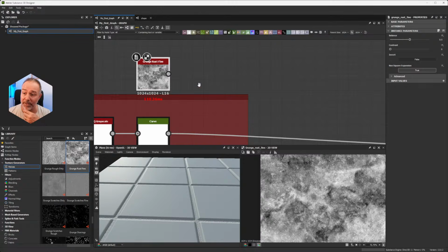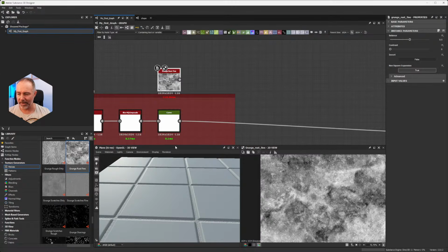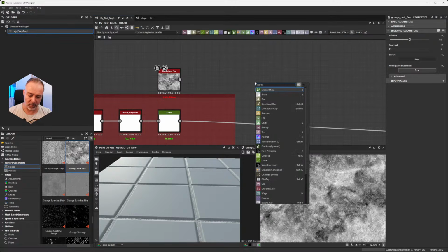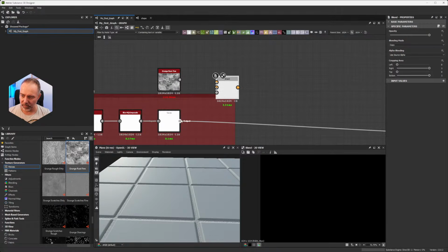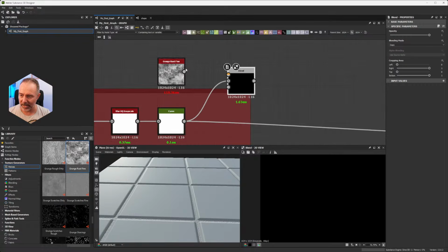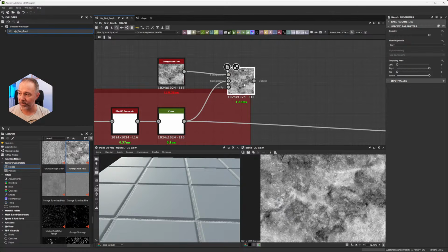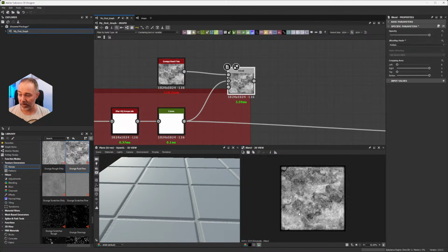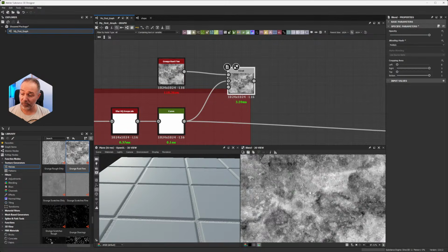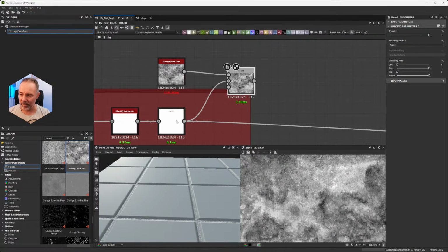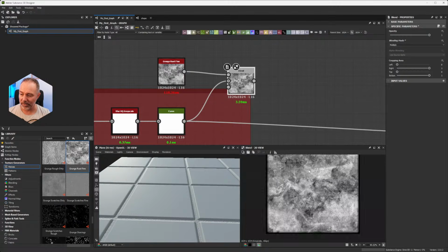And this I will use to warp. First, I'm going to blend them together, so I am adding some information here. We put a blend node. I'm going to put the tile as the background, this as the foreground, and I'm going to go to multiply. Multiply does a multiplication of values between 0 and 1, so all the white will be multiplied by this; white is 1, so it gives the same thing.